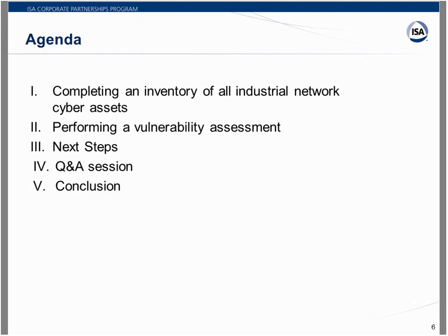So why is inventory the first step? Almost every one of your cybersecurity program standards starts with an inventory. The NIST framework, which was just completed in 2014, identifies that as one of the first steps you put together. ISA 99, which is now 62443, an IEC international standard, establishes that this is fundamental: you create a network diagram. So first, let's talk about what that actually means.